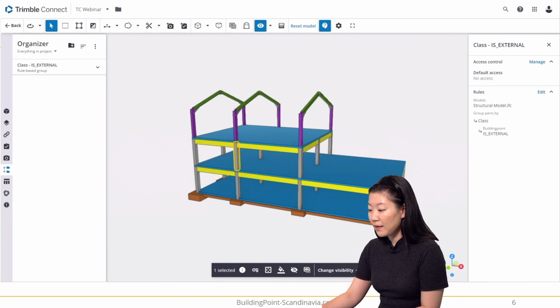And just a quick tip here, the BIM coordinator should be familiar with the information that is contained in the model. This way they can use the information to group the model objects or for other purposes. And what kind of information should be included in the model objects highly depends on the specific needs of the company or client. For example, if the intention is to use the model for material takeoffs, certain attributes should be included in the model objects. These attributes might be length, volume, weight, and so on.